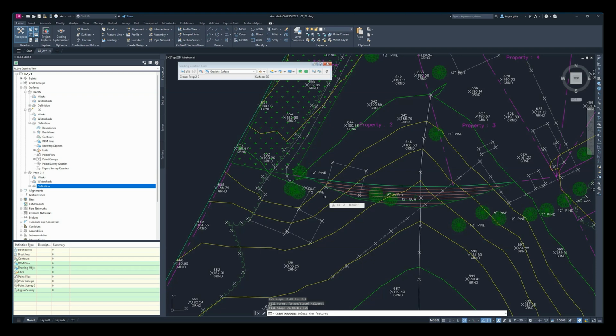Where's that water go? But I digress. When we bring in that earth, developers, as much as they may want to, can't just bring it in and say, okay, I'm filling here, stop. You've got a new rectangle of earth that exists. It would all wash away. It's going to degrade over time. It's a safety hazard. There's 1.5 million reasons why you don't do that.